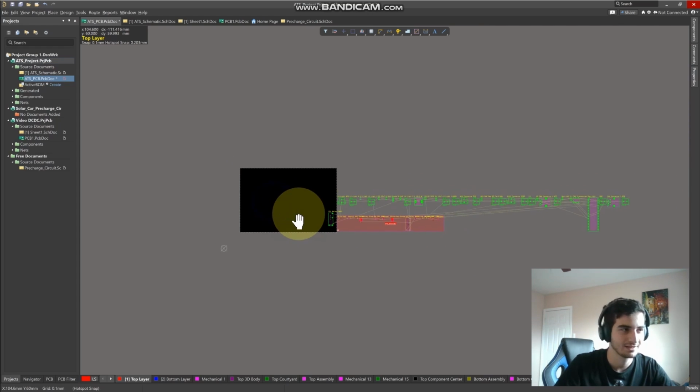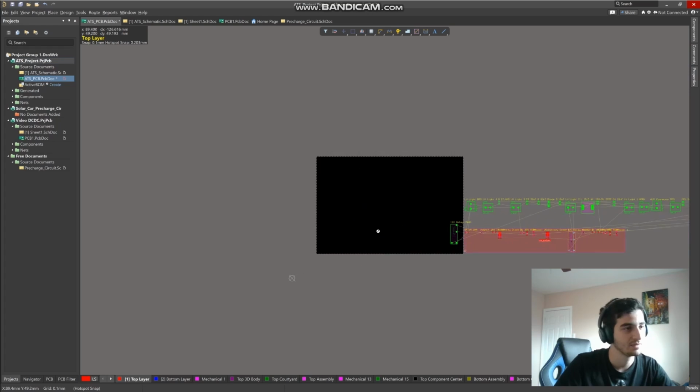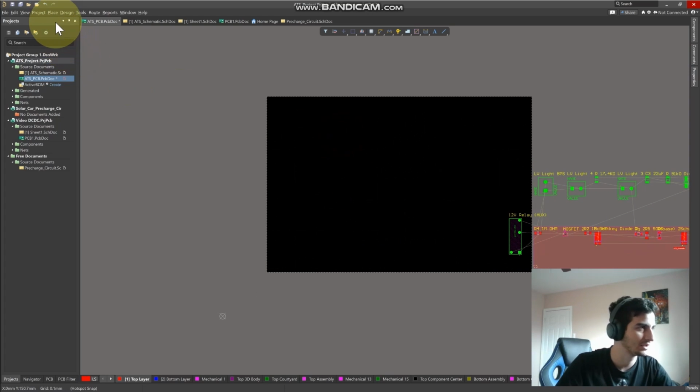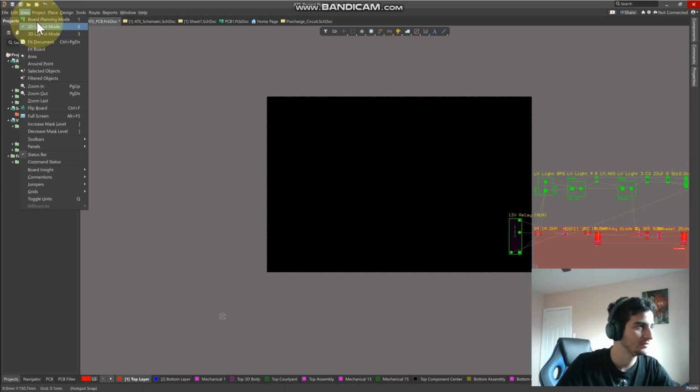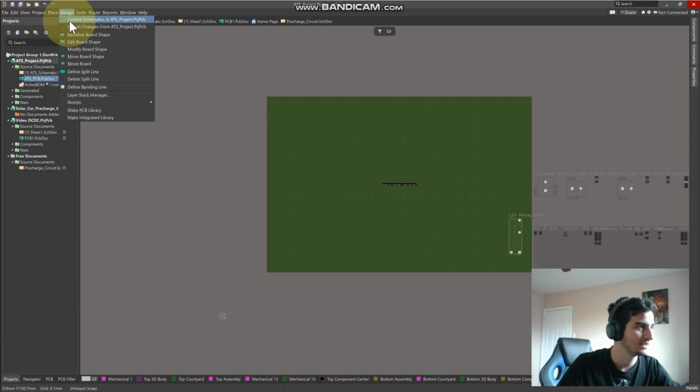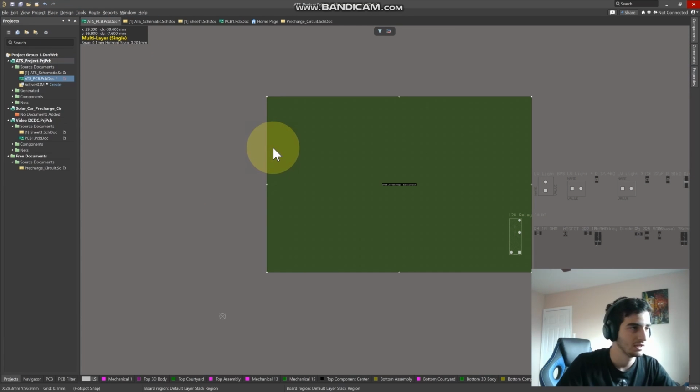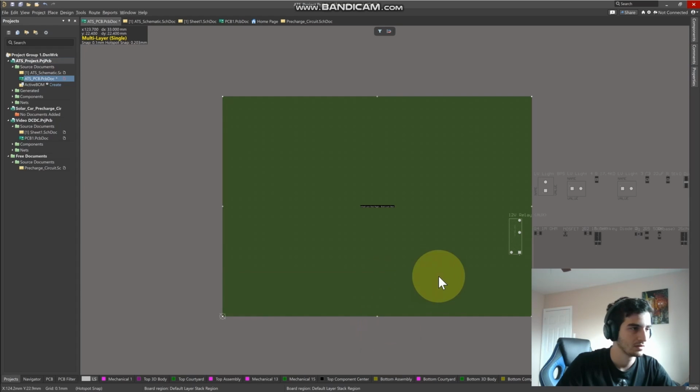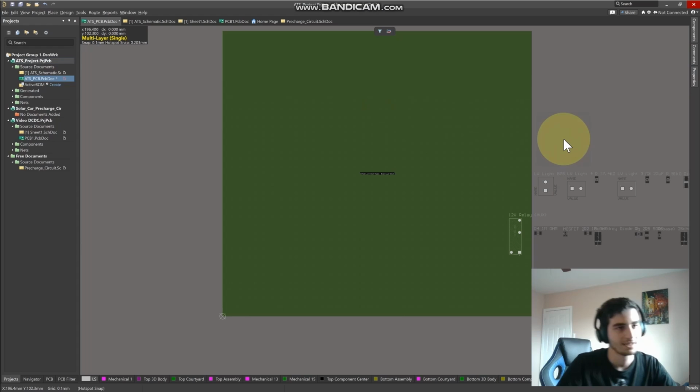Maybe you already realized we cannot fit this in here, so we might need to make this board a little bit bigger. What do we do? We go into View, Board Planning Mode, Design, Edit Board Shape, and you can simply make this bigger. Let's just say this is good enough. I don't want to take too much time.